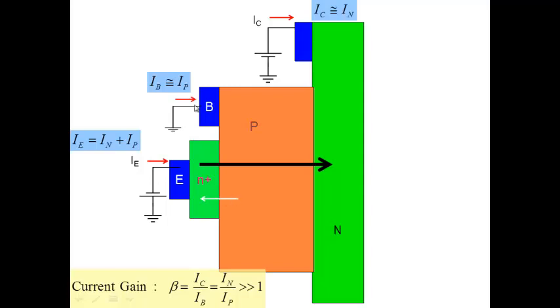As it forward biases, if this current source will forward bias this junction, then as this current flows, this also has to flow, because the two are related together. And therefore you end up getting a collector current. So in that case, what are you doing? You're controlling the collector current through a base current. You inject base current, and thereby you control the collector current.